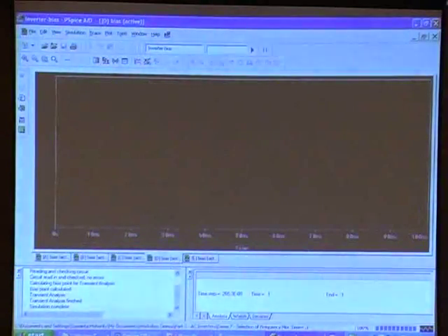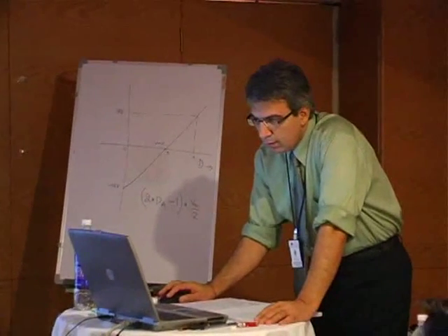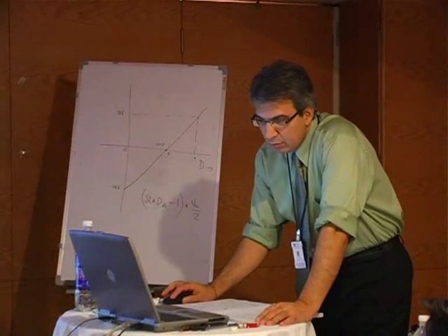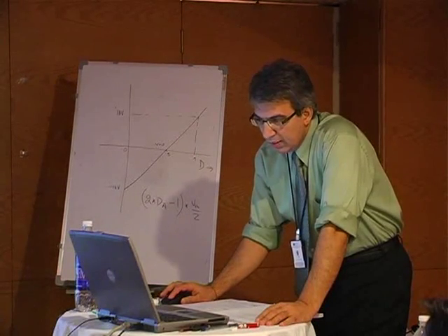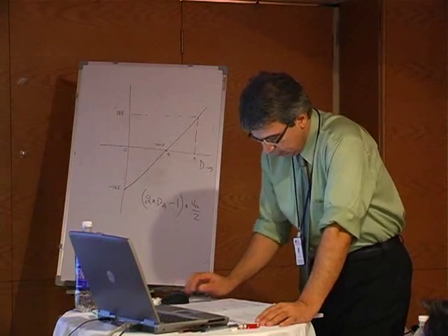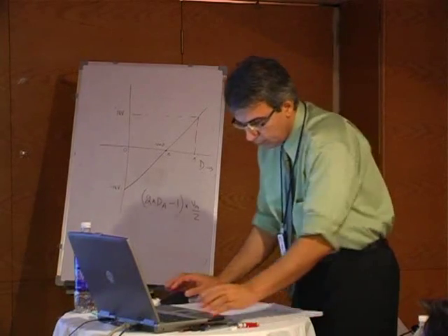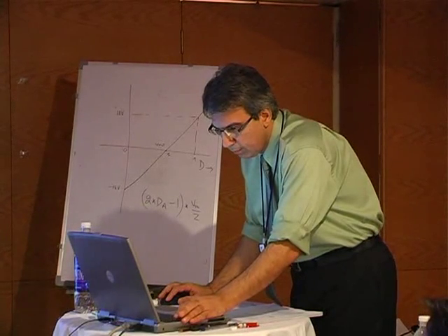All right, what else do we want to see here? Let's plot the harmonics now. There are two important voltages you look at for harmonics. One is the voltage between VA and this middle point of the inverter, and the other one is VA to the neutral of the motor. So we can look at these.